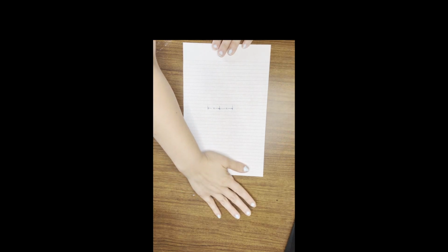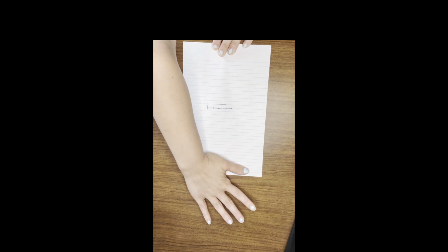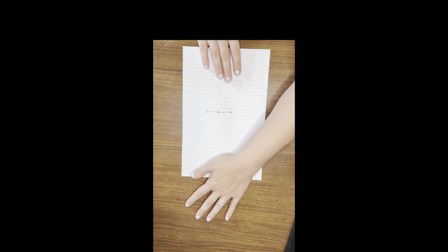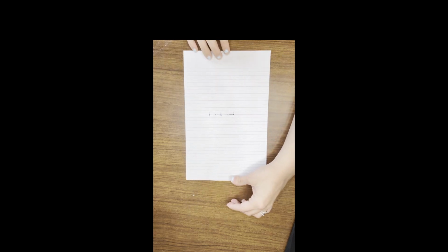And it's not going to be infinity, right? Because if I put a load on here, I can pull this apart and it's not cracking, or tearing. So that means that our stresses at the ends are not infinity when I put any kind of load on this. I still have to achieve some sort of stress or reach some threshold, or what we would call a critical stress intensity. So I have to reach a critical stress intensity at these edges in order for it to ultimately tear.